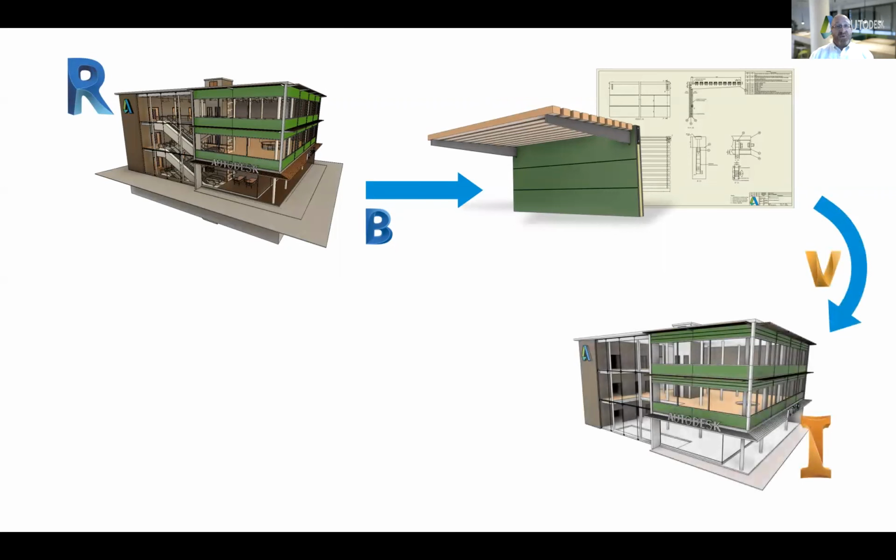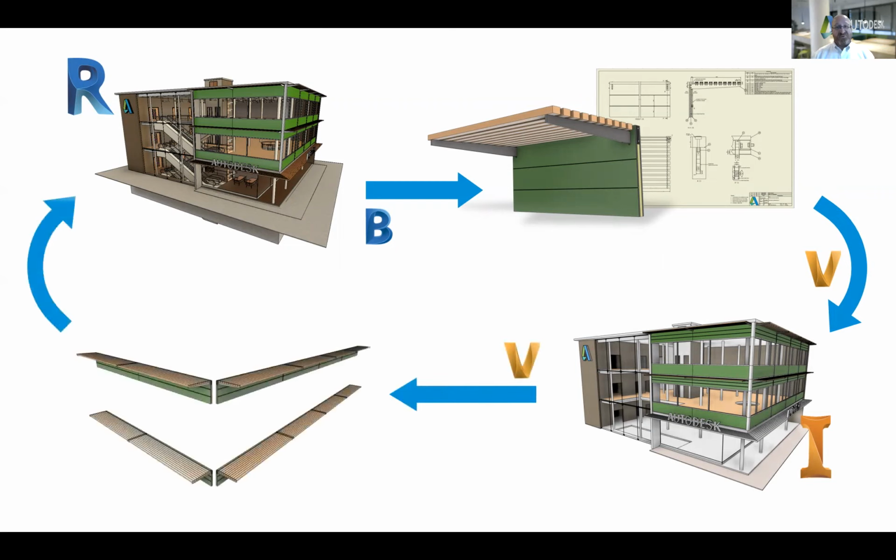That can be synced with Inventor, referenced directly into that software, so that what you are seeing is actually the Revit model, the designer's model. You can see the architect's design intent in there, and those elements get replaced with the Inventor models that you are producing. When the manufacturing models are positioned and sized correctly, then you can see how they can be exported back again as native Revit geometry or as BIM neutral file formats that other software can bring in.